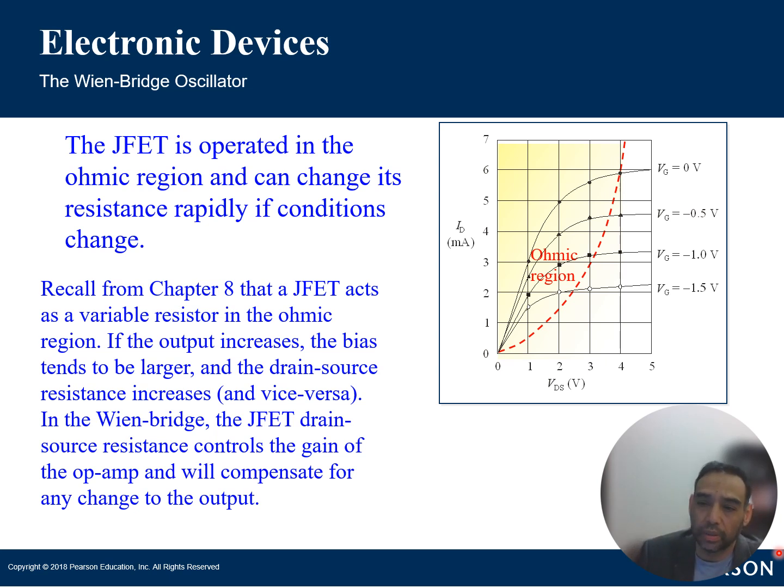If you look at the channel conductance of the JFET, which should be below the threshold voltage, the depletion region between that gate and the channel remains wide. And then the channel between the drain and the source is only, if you remember from your textbook, weakly pinched off, right? So it pinches that current. So what this does, it allows the current to flow through the channel, and then the JFET operates as this voltage-controlled resistor.